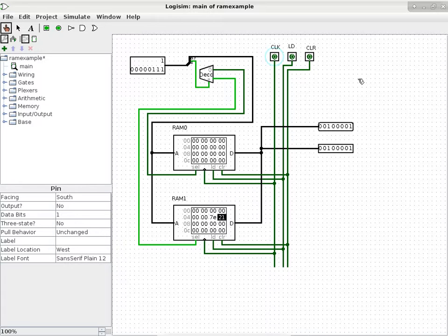Increment, exactly. So what you want to do, I cannot show it here because they don't have the actual component here. We can make it out of basic components, but it doesn't have it here. So what you want to do is make your RAM chip a little bit smarter. The RAM chip will now have more control lines, and it will also have a more complicated circuit on it. The processor can say, I want to get into burst mode for the next few operations. The burst mode is specified using its own dedicated signal line, to specify that this is a burst mode operation.